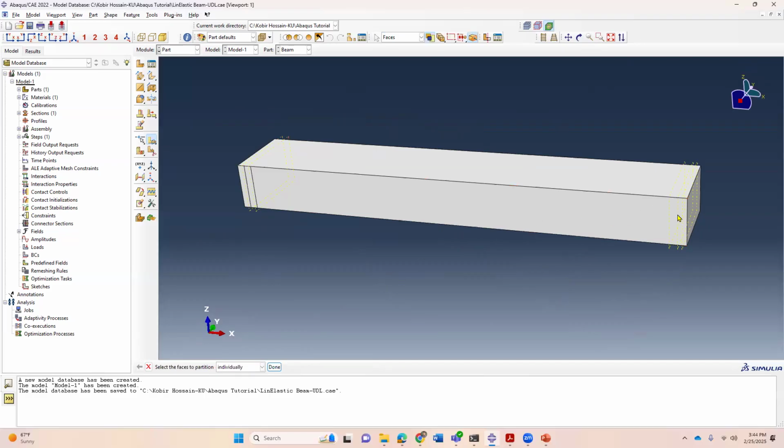okay. And now also this surface, yes, first one, yes, then the remaining one and the other surface. So if we have an extra datum plane, that's okay, it's not doing anything. Or if we want to delete it, we can come here, delete feature, and then click this option, done, it will click, okay. It will delete that part.